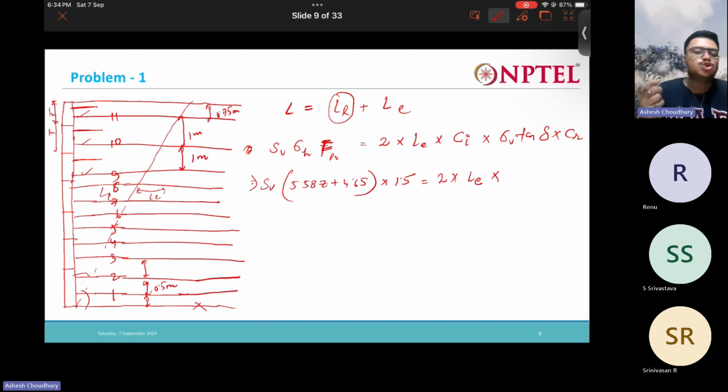But when we use a geogrid, there is an interaction coefficient that we have to use, which defines the interaction between the aperture, because there are holes in the geogrid, the soil, and the material of the geogrid. This coefficient comes from the interaction between all those things, and it is determined experimentally.